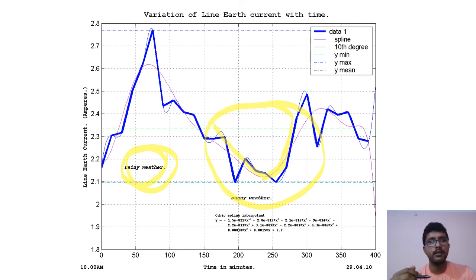So we can compare a particular sunny weather condition for several days. And if the trend goes on rising, we can perform hotline washing or cleaning of the switchgears after taking a plant shutdown for 5 to 6 hours. So this is how trend monitoring is so helpful, right?